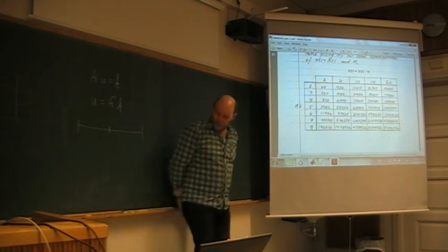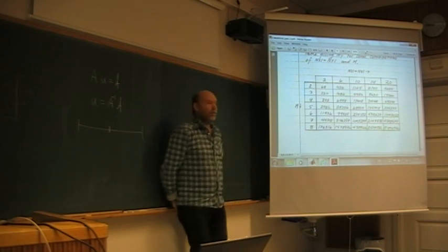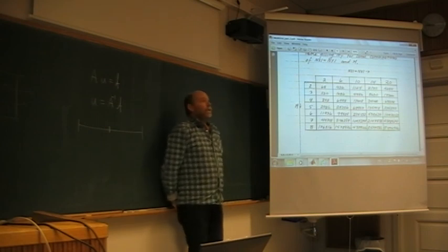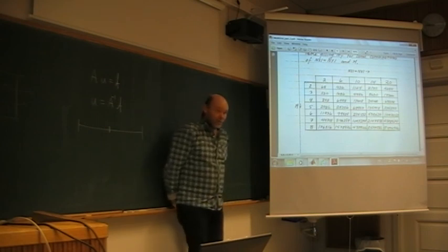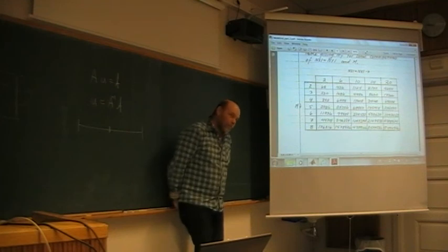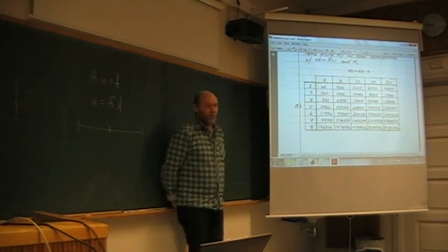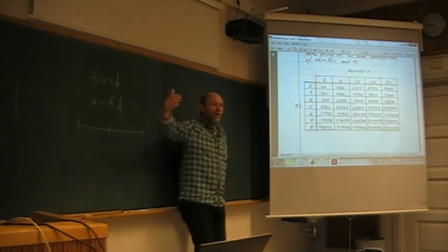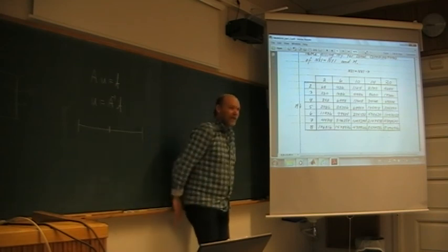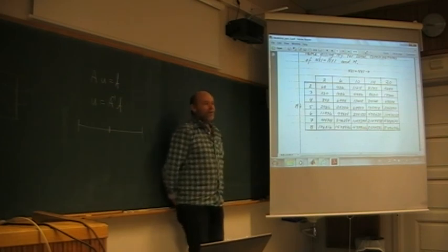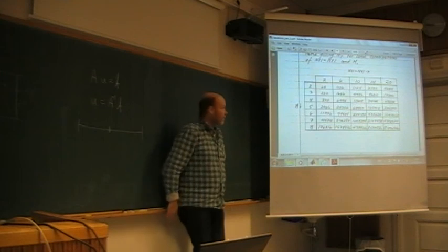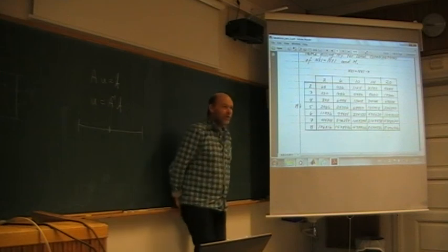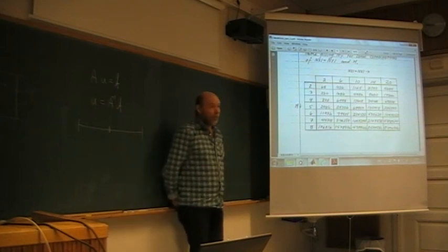But remember, I think I've said it before, a parabolic equation system or a hyperbolic equation system can be solved where you march the solution forward in time or along the characteristics. It's elliptic equations that are expensive. That's where you need CPU. That's where you need a fast solver. So elliptic problems only.